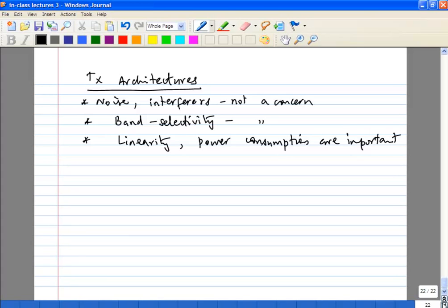Okay, so at the receiver you are interested in receiving, so signal values you are receiving are in microvolts. Okay, maybe even smaller than microvolts. Here on the other hand, the signal going into your transmitter from the baseband will be in several tens or hundreds of millivolts. Okay, you can see the dynamic range difference. So you are far above your SNR requirement. Your SNR requirement may only be from your digital baseband, may only be like 10 or 15 dB, maybe 20 dB maximum. So you will be much higher than that. And remember you are actually transmitting into a background of noise, right? And as long as you transmit high enough power, that won't be a problem.